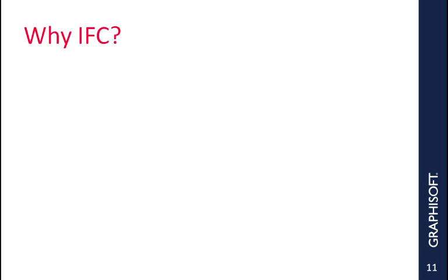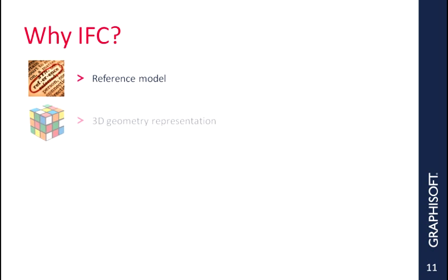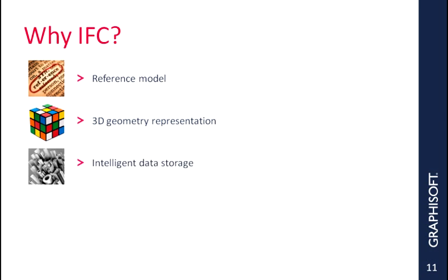Let's review some of the IFC benefits. IFC supports the reference model concept. IFC provides 3D geometry representation for all project elements. IFC also stores standard and custom data about each element, such as materials, profiles, functions, and so on. The applications used by the disciplines can easily and quickly filter and identify the relevant discipline-specific information from the IFC database.